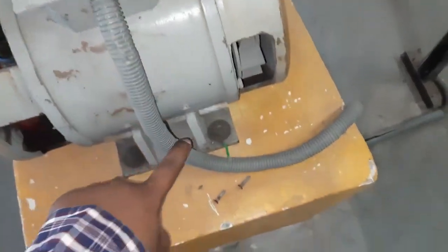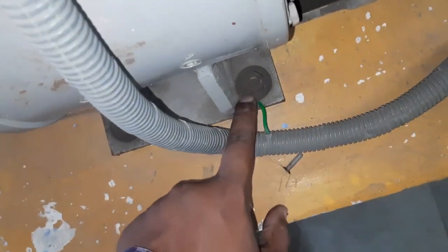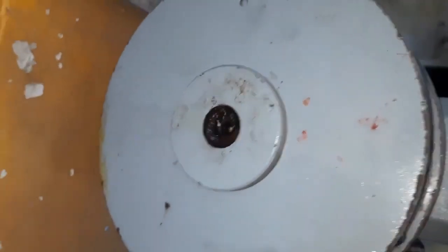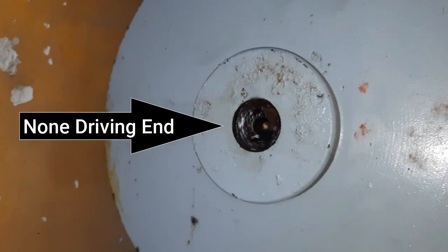Now you can see this wire is going towards the panel, but there is also another wire which is connected to the body of the generator, which is the green wire. We usually use it for the earth system, so that if you have any leakage, then the leakage will be transferred to the earth. Now this is the non-driving end of your DC generator. If you see closely, here you will also have a bearing, which is totally greased in order to reduce the friction.